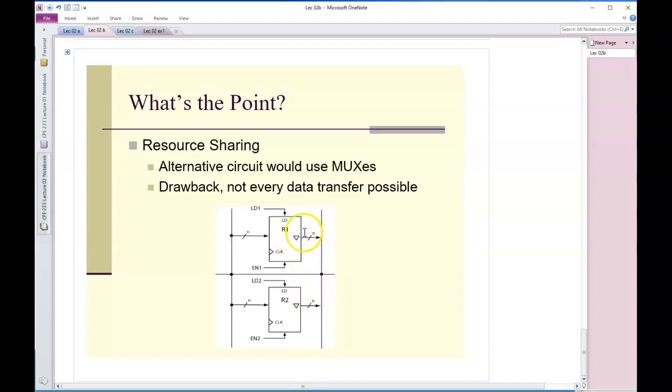You can see that both registers have the ability to drive their data onto this single line here simultaneously, which they don't, of course. Two registers driving their data onto a line simultaneously is bad news. It's called bus contention. It's just not going to work. So only one of these registers at a time, or only one device per shared resource. The shared resource here is this line right here, or whatever it's connected to. Only one device can drive its data onto that line at any given time, and I cannot swap data into these registers simultaneously the way it's set up.